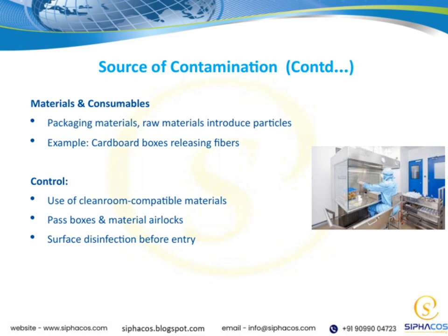These are often overlooked, but they can be a significant source of particles in the environment. For example, packaging materials like cardboard boxes can release fibers into the cleanroom. Similarly, raw materials themselves can introduce particles if not properly managed. To control this, we need to focus on using materials that are compatible with cleanroom standards, materials that don't shed